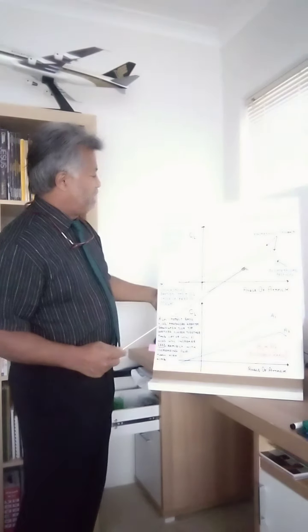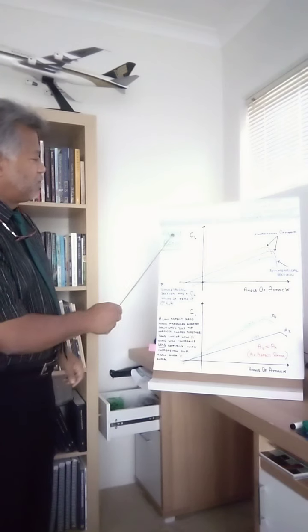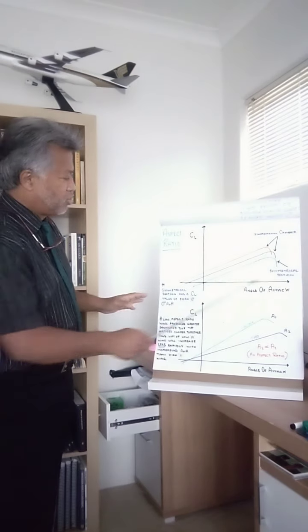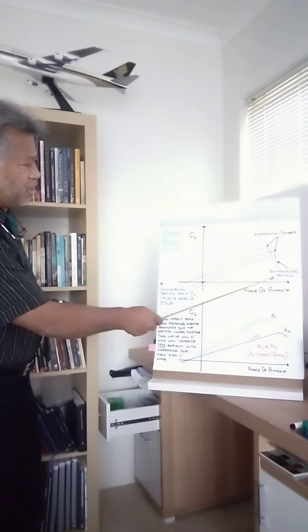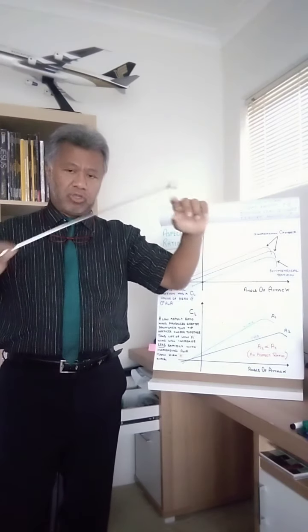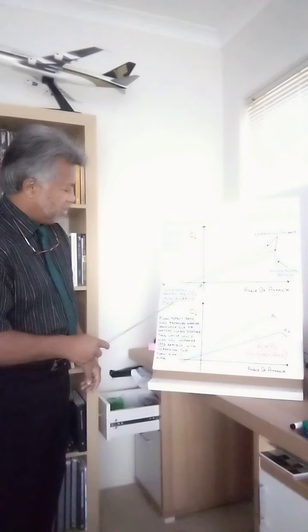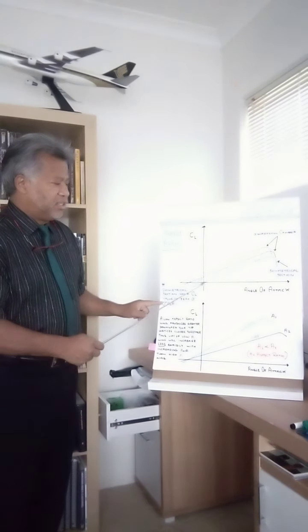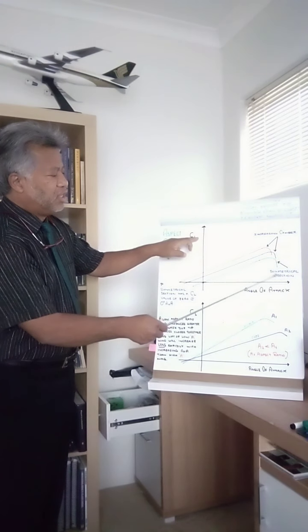So it's the shape and the angle of attack. Alright. The other thing that affects the coefficient of lift depicted on the graph here is the aspect ratio, as well as the camber. If you look at this first graph, you'll see the coefficient of lift drawn against the angle of attack. You notice we have a symmetrical aerofoil, which has a similar shape top and bottom and creates a similar pressure, so the coefficient of lift is zero. So a symmetrical section has a coefficient of lift of 0 at an angle of attack of 0. As we increase the angle of attack, the coefficient of lift increases for a symmetrical section.